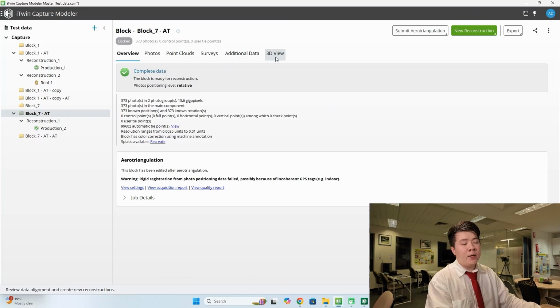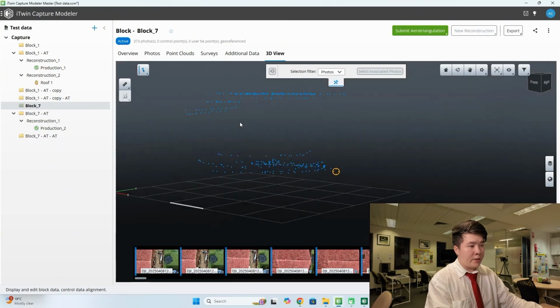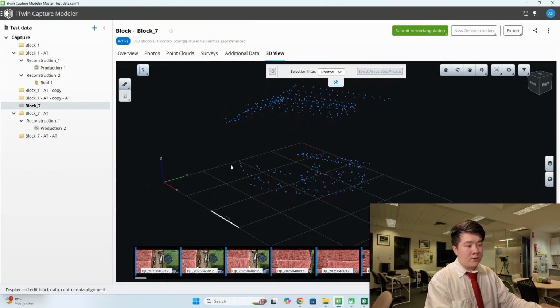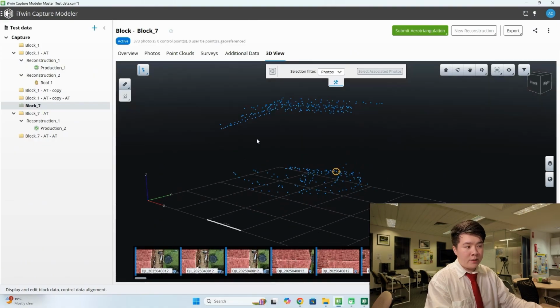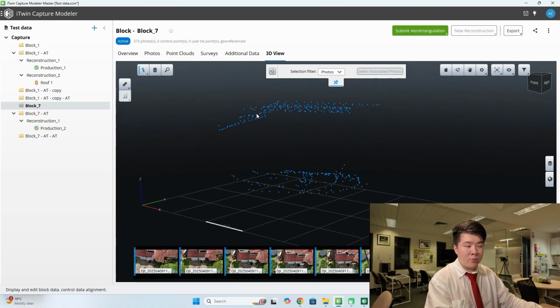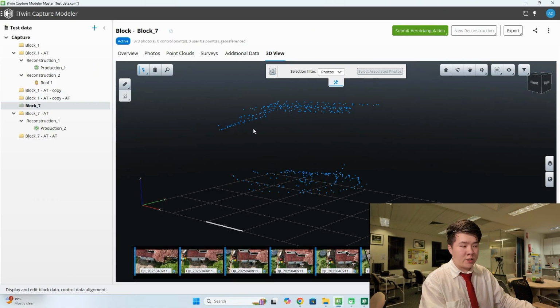So what that means is that although it has finished aerial triangulation and is ready for reconstruction of a reality model, it is unable to georeference it. This is likely caused by the fact that there is a split between the oblique and the nadir capture, especially in terms of height. So if you are really dead set on having georeference, you can always manually bring each data point up. But you can see that for bigger projects, this becomes impossible in terms of practicality and time.